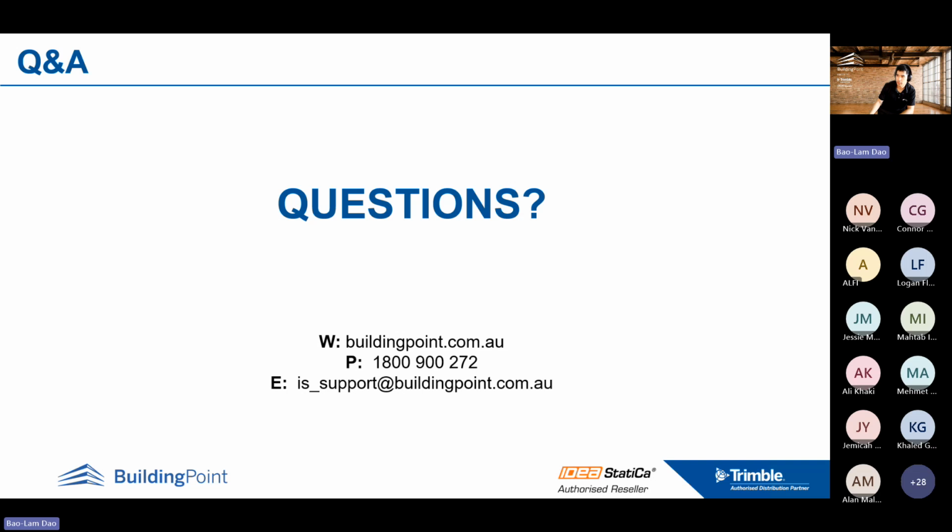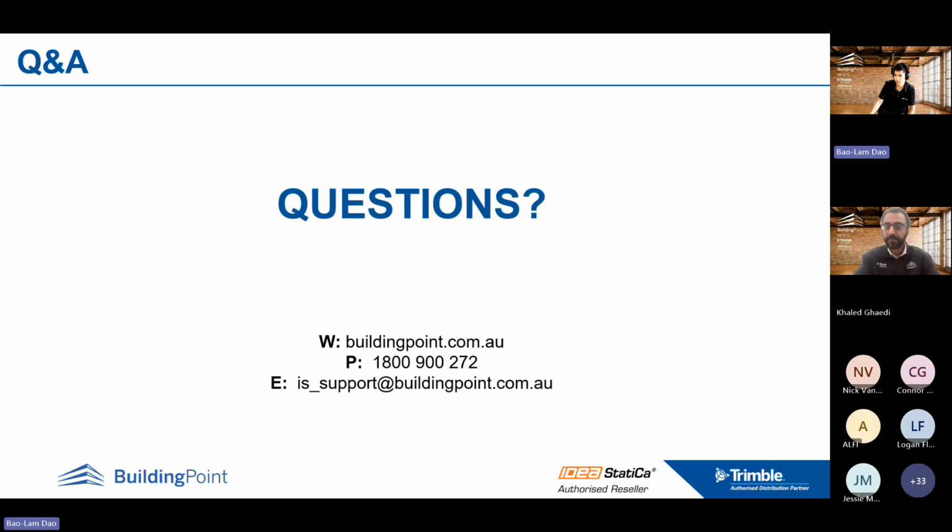First one from Debray. He's asking if the software has a steel section or connection with external post-tensioned connection. I believe you're probably asking if IDEA StatiCa can handle steel connections where external post-tensioning is applied. We have Nick in the room who's our steel expert, but I think the connection module itself primarily handles steel-to-steel connections. When it comes to applying external post-tensioning force to that connection, there needs to be some sort of workaround. You probably have to represent the effect of post-tensioning as additional forces or moments applied to the members and nodes themselves. The software is not designed to have full interaction between the steel connection and the post-tensioning effects. That is my view on it.